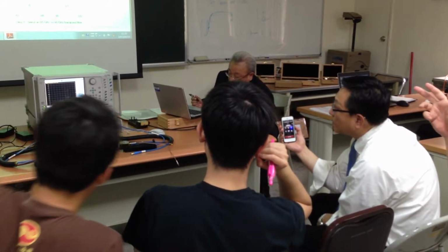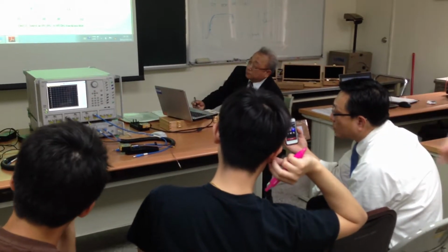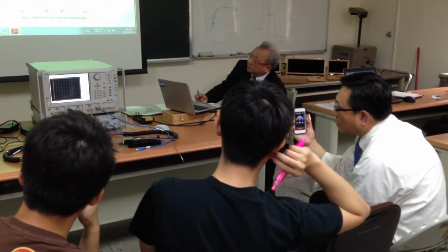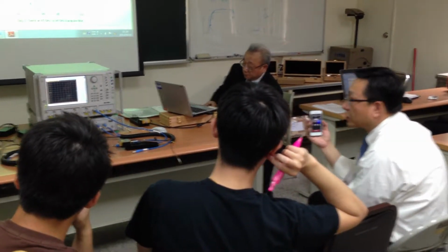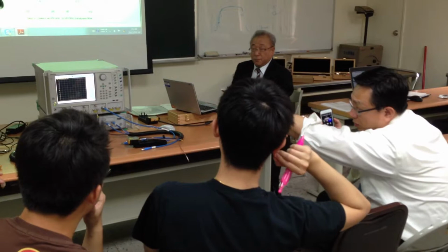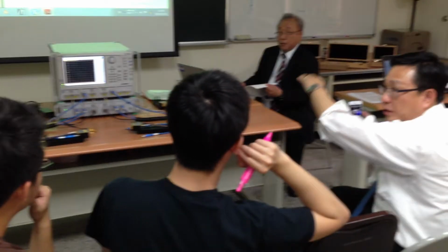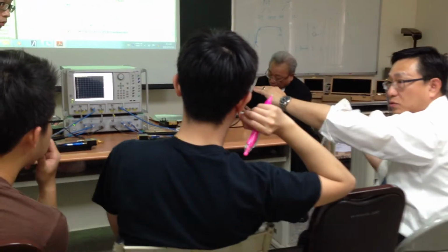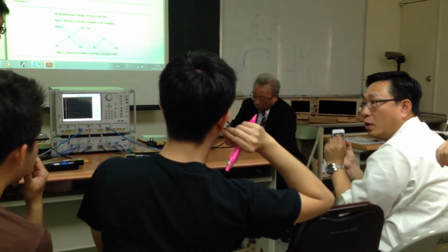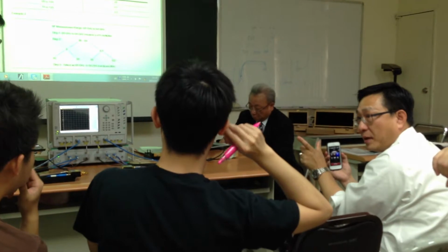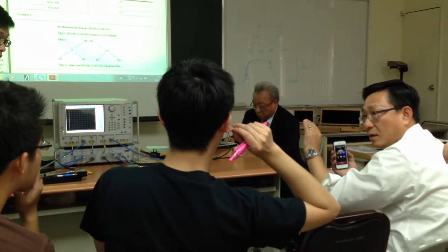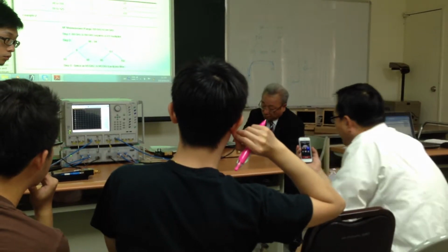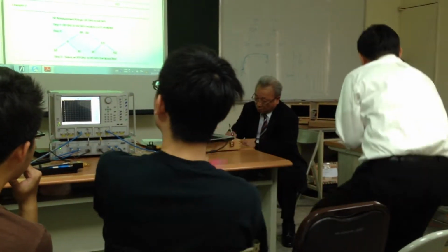So it sort of implies both the gain is flat to within a dB or so of the noise figures. So in the noise figure trace, within 1 dB of variation, for such a flat device noise figure curve, you can use a wideband pass filter, and then remove those images mathematically. Okay, so that basically solves our question.